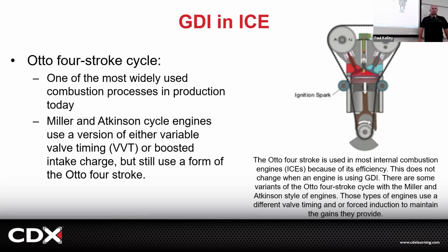Now, of course, if you're under wide open throttle, you close the intake valve. Let's get a full 2-liter of power. But if you're going down the freeway or just not really accelerating, just coasting on this side road, we're going to drop that down to like a 1-liter by hanging the intake valve open. Then once the intake valve closes, we still need fuel, but we only need fuel for 1 liter rather than 2. The direct injector will spray the correct amount of fuel at the correct time after the valve is closed. It's pretty interesting how they've done it.